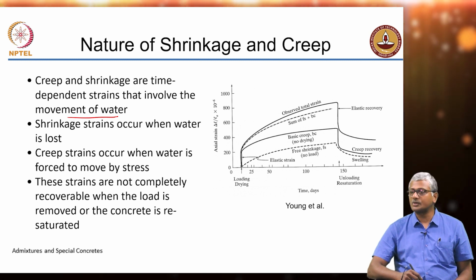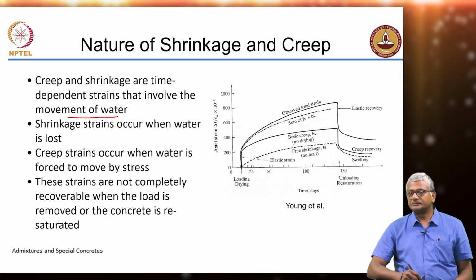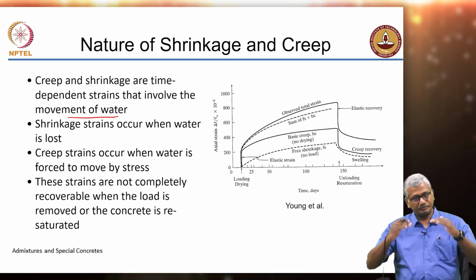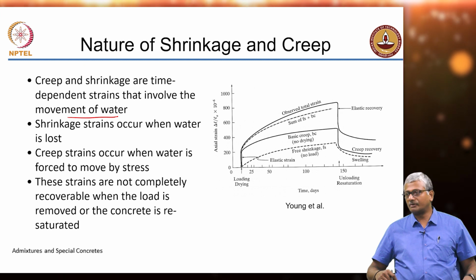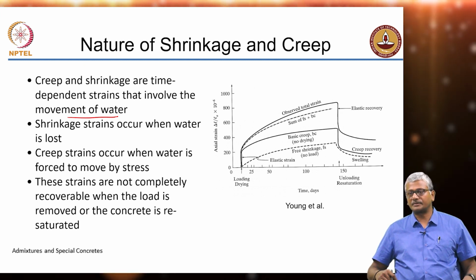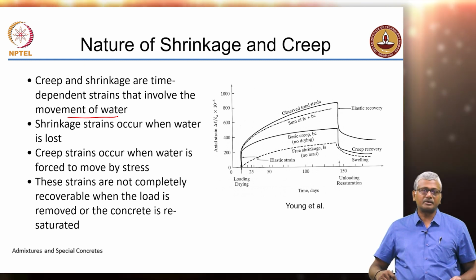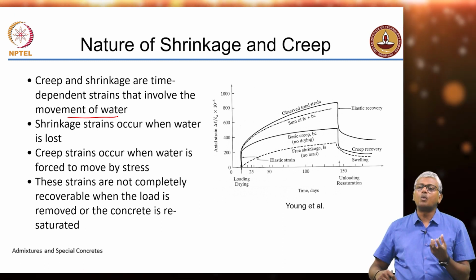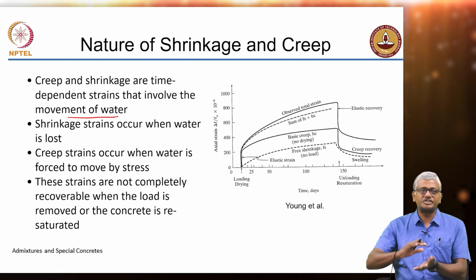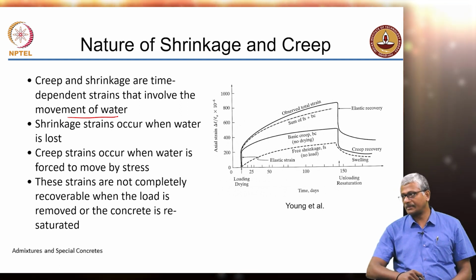Why do soils consolidate? Because with the effect of the load over time, there is dissipation of the water that is underneath in the soil, okay. Similarly, in concrete, the longer you keep the load, the water inside the concrete tends to move around and that adjusts the structure of your concrete, okay.